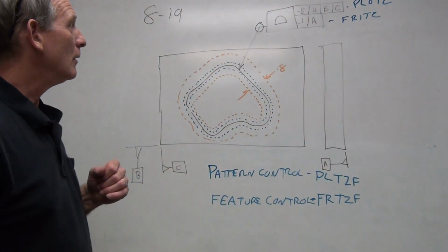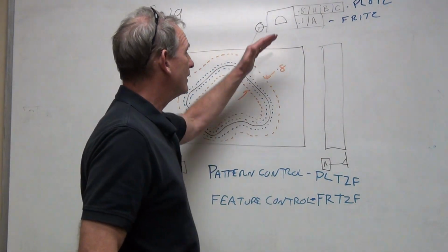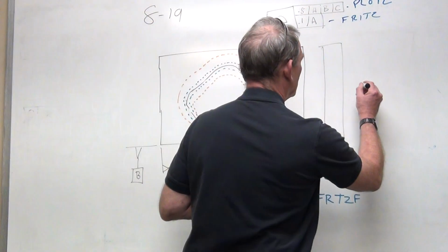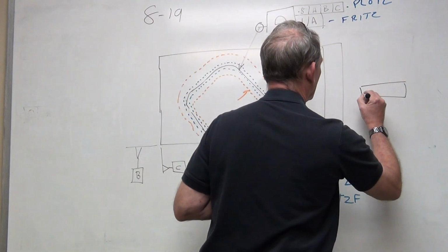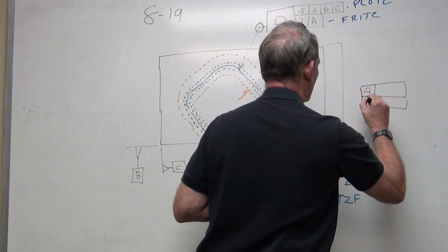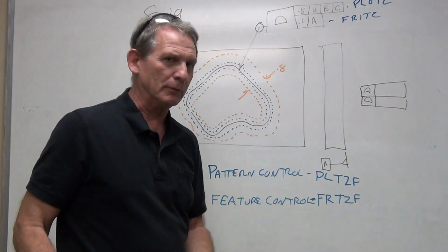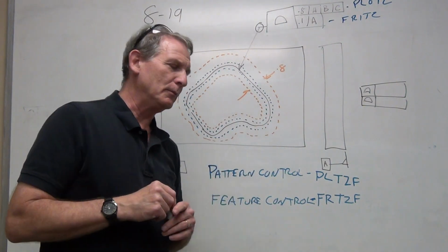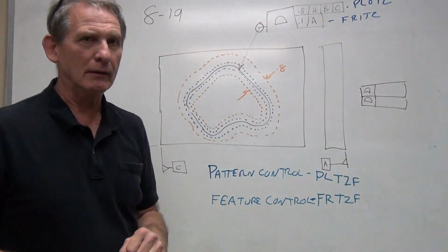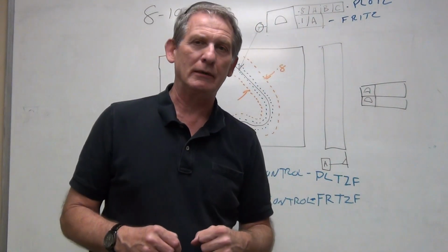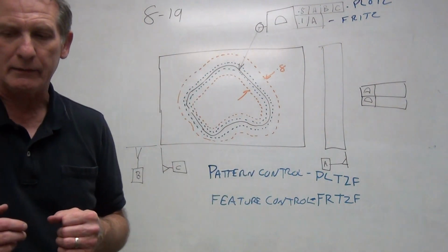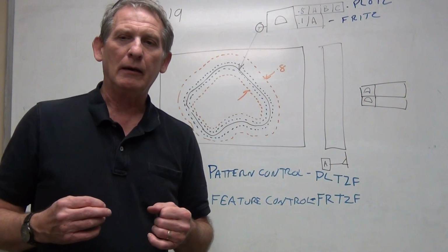positional controls, we'll see that we'll be able to actually stack two separate feature control frames, one on top of the other, where we don't have a single symbol. So it does get a little bit more complex. I just want you to recognize that if you have the single GD&T symbol, it is a composite control. Okay, so we're going to leave profile at this point.